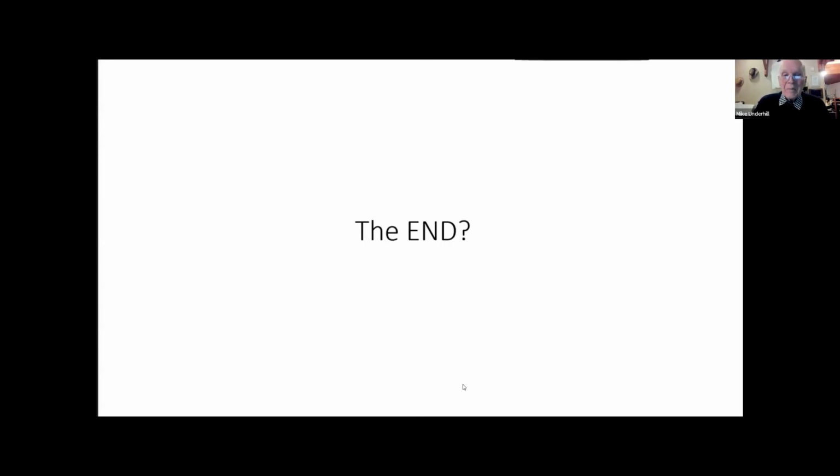Okay. Yeah. Now, why do all the antennas use gold plating rather than cheaper base copper? Does gold behave better as an antenna? No, it's oxidation. It's oxidation. So you look at the copper, and they usually put some other metal, like maybe tin or nickel, on top of that, and it oxidizes.